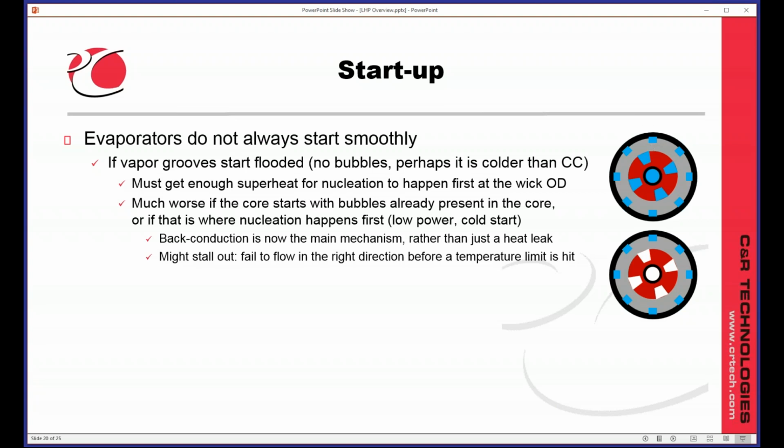So it would take a bubble in the right spot or nucleation spot. And in fact, it's possible to have the loop start and operate, and this zone in here stay superheated. Same thing in this. So you can actually have this loop start and operate, and this is actually where vapor is forming, not here. So unfortunately, it's one of those things where you have to not use wishful thinking about where a bubble should form. The darn things will form where they want to.